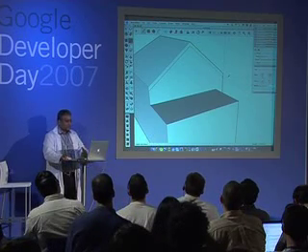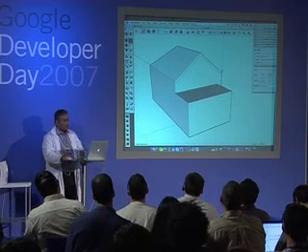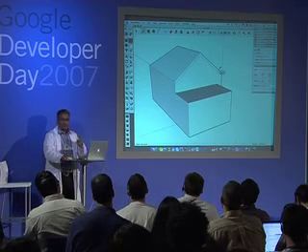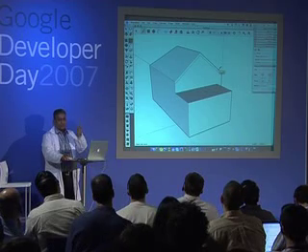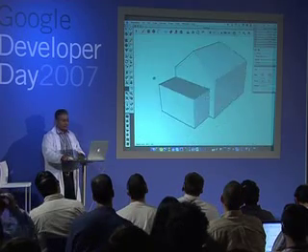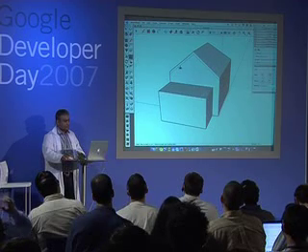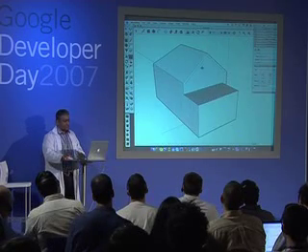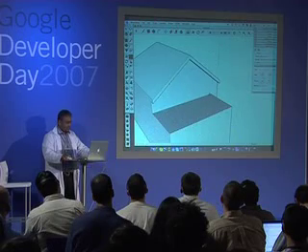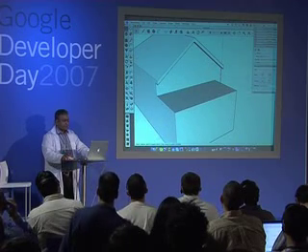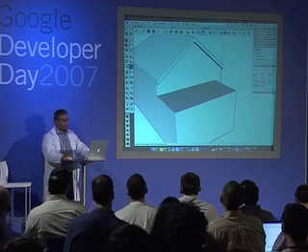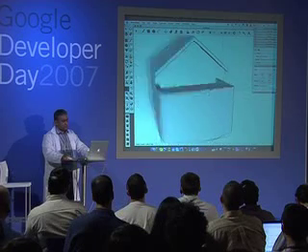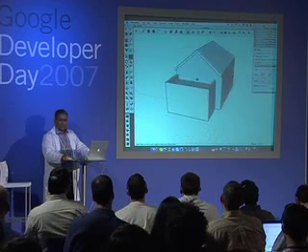Okay. So far, using this much, I have maybe used 3 tools, 4 tools. Draw the shape, push the shape, move it, and line tool. Okay, and I've got a 3-dimensional shape there already. So I can take that shape and pull that out, put some detail in. Maybe I want to put a parapet wall. I will select that line, and that line, and use my offset. Maybe it needs to go a bit further down. Okay.